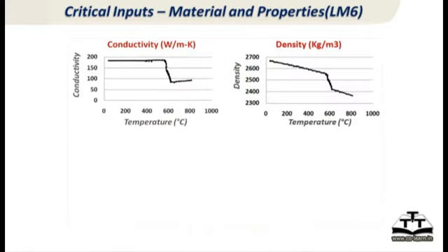The first stumbling block itself is the material database. What people don't realize is the material properties can change drastically. As you can see, the percentage difference in just conductivity. Look at the difference. It's almost half. Okay, density changes by 10-15%, right?